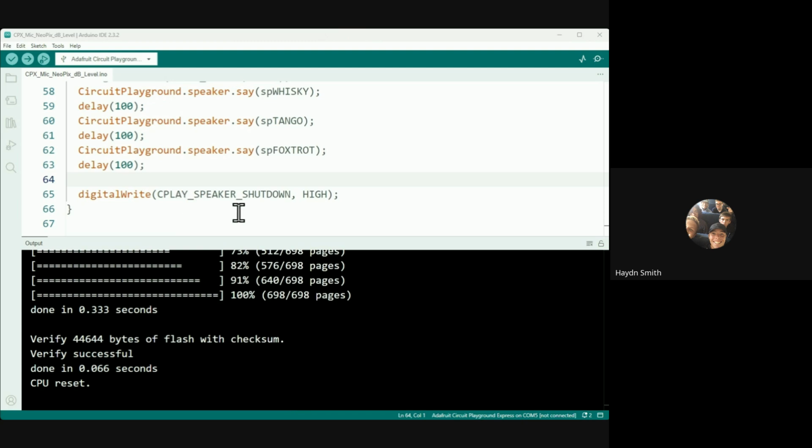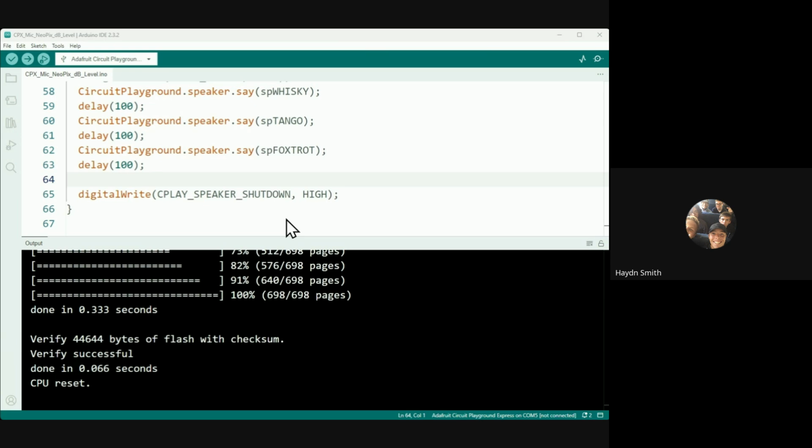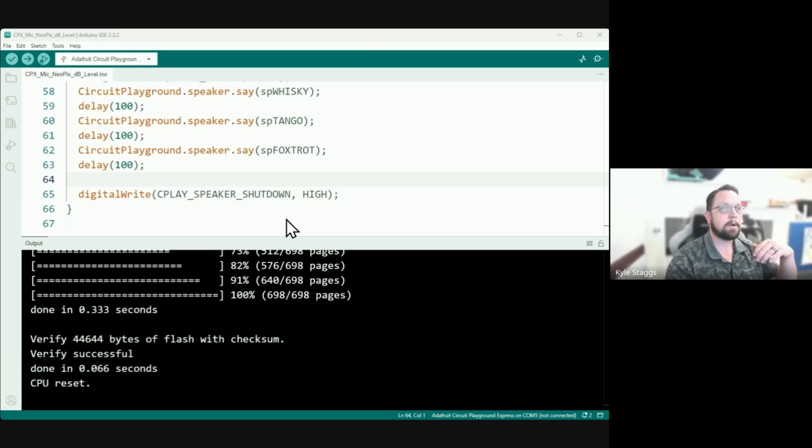And then the recording data is that one, you're writing code that records audio input and plays it back? No, it's not playing it back. The recording data is measuring data from the light sensor, which we've already done. Oh, that one. Yeah. And it's looking for you to take 100 total samples with 100 millisecond spacing, and then plot that on the serial plotter in order to see what the sensor is bringing in.